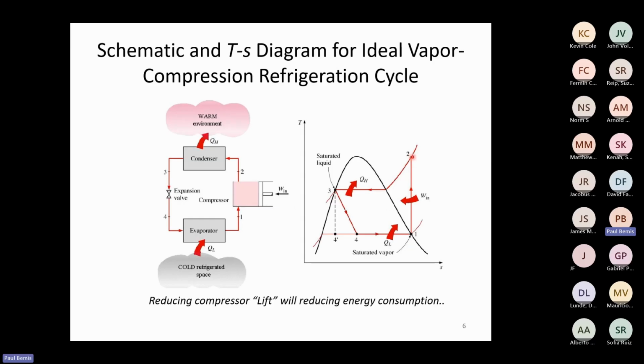So we compress up and then we come down. This is phase change. So we're going through isothermal change here, phase, because I'm using phase change to absorb that heat, or eject it in this case. Then I drop down. It's actually, this is the ideal path here in the dotted line, actually some entropy growth. We won't go into entropy growth, but here I'm down on cold again. So now I'm going to dump the data center load that's coming out of the data center into that loop using the evaporator. So it gets hot, again, isothermal phase change, and then back up again. Same cycle you see in your refrigerator in your home. Same cycle you see in your heat pump in your home.